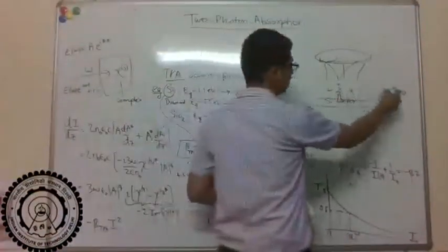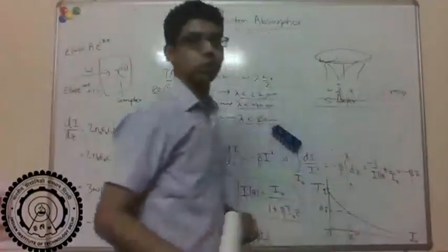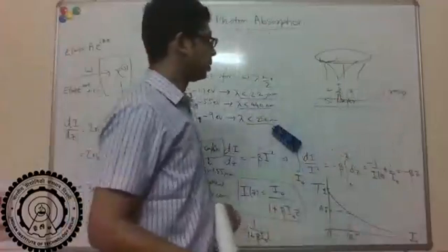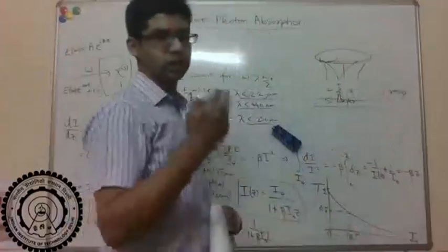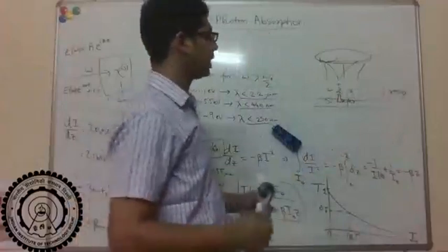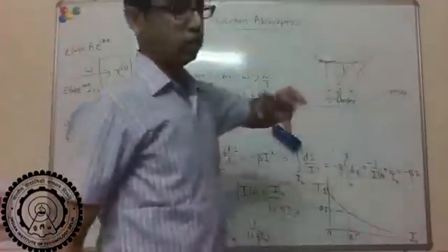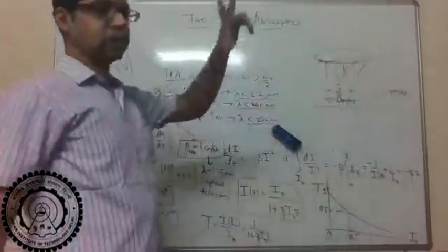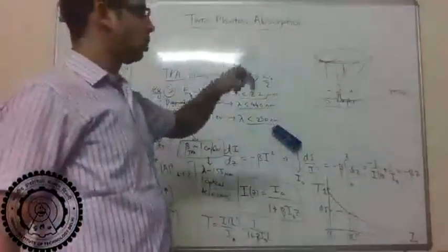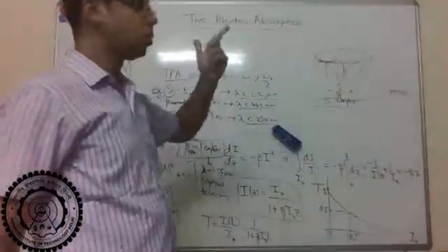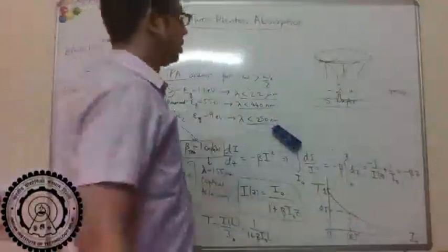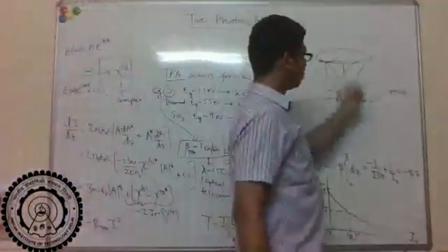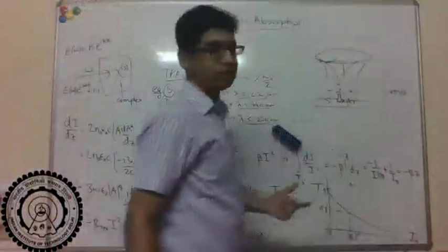So again, let's say you have some resist which works on 2-photon absorption. So it only absorbs 2 photons. It doesn't do the linear absorption. So let's say it has some absorption levels which are more than the single photon energy, but lower than the 2-photon energy. And so it undergoes 2-photon absorption and undergoes this chemical change.